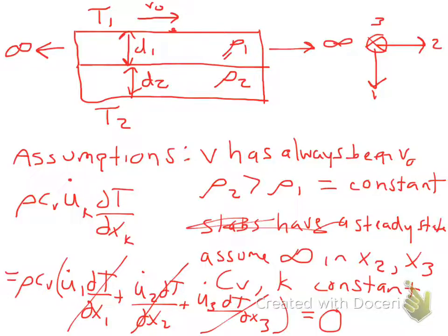And on this one, U1 is 0, even though there's a temperature gradient in that direction. So that's good. I mean, that's one point that I think is really easy in a more complicated problem to be like, oh my gosh, how is this? There's all this movement of fluid around or something moving around. It is a very good thing to recognize that it's the movement within the direction where there is a temperature gradient that matters. If there's no temperature gradient in that direction, it doesn't matter.